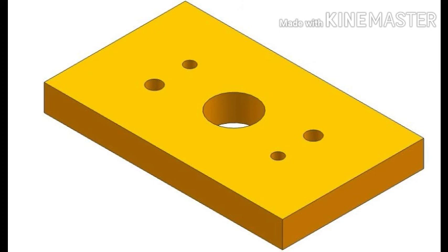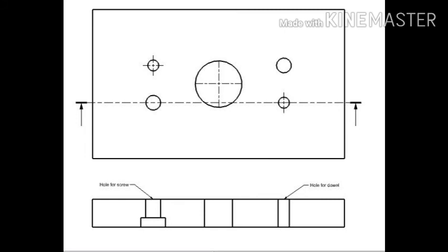Friends, now we are going to see the bottom plate. You can see in the image. The bottom plate gives a cushioning effect to the die. It provides space for the tool to be clamped to the press bed by the use of toggle clamps, screws and bolts.